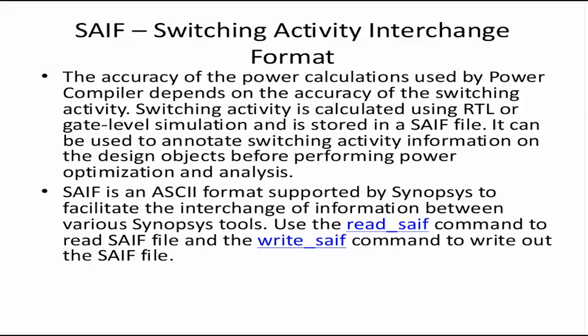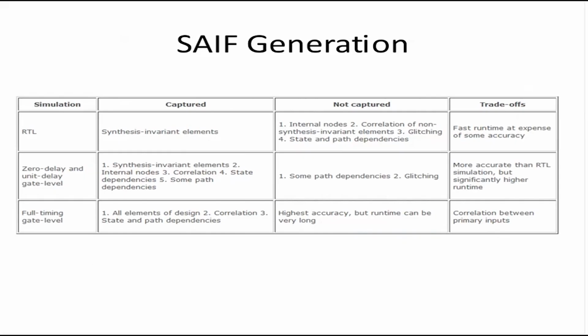Right? So the main aim is to provide accurate switching activity, and for that we need a good stimulus, right? Good means a mission mode stimulus, a mode which mimics the real world application, right? So we generate the simulation data.